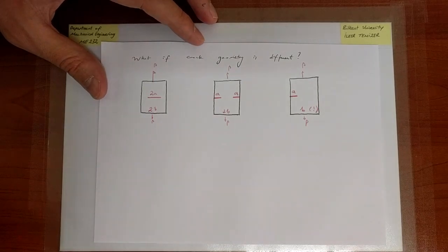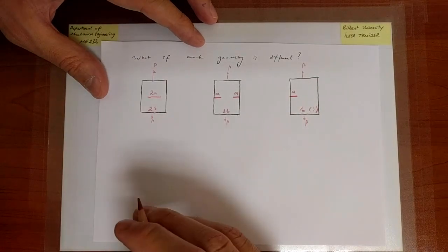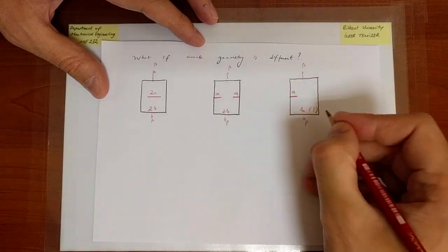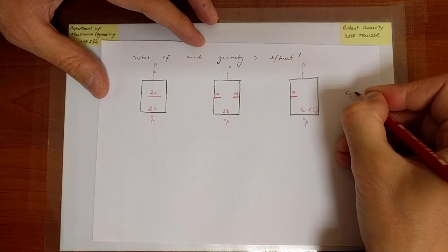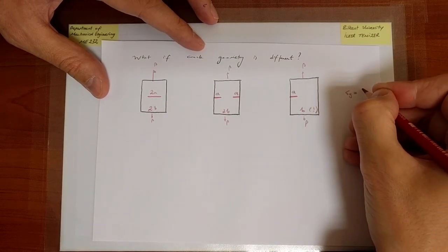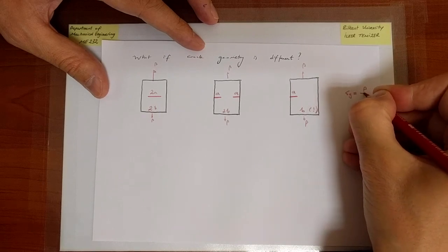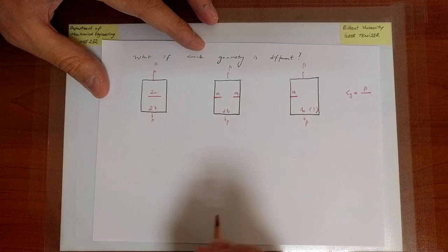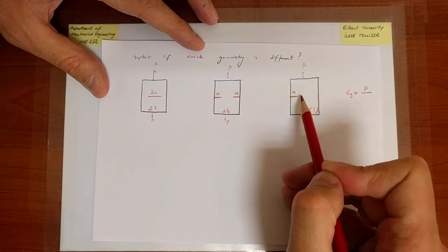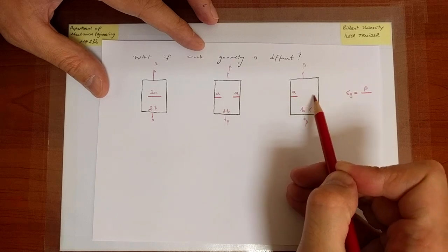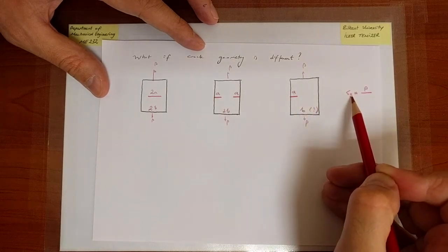Okay, now, in all cases, SG is defined to be P divided by the area. Okay, now the area of the cross section, but where we omit the presence of the crack. That's the idea of the gross stress.